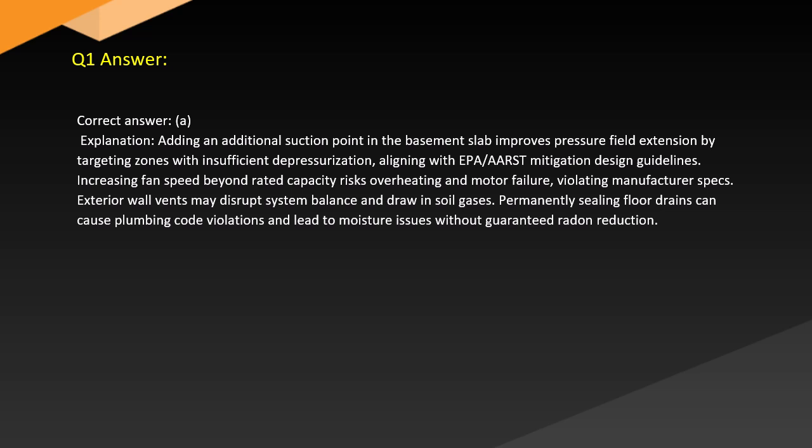Increasing fan speed beyond rated capacity risks overheating and motor failure, violating manufacturer specs. Exterior wall vents may disrupt system balance and draw in soil gases. Permanently sealing floor drains can cause code violations and lead to moisture issues without guaranteed radon reduction.